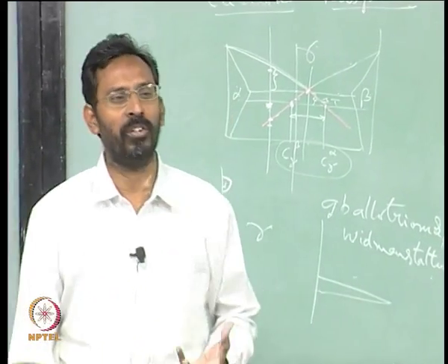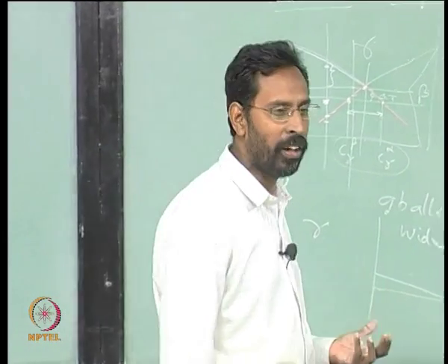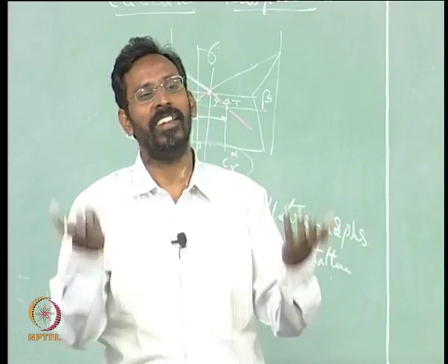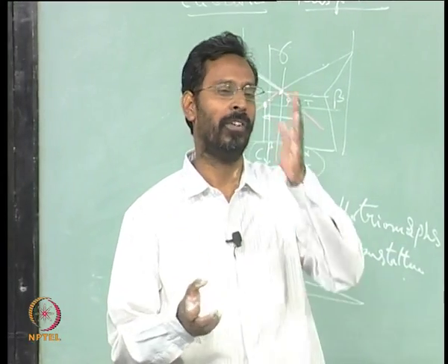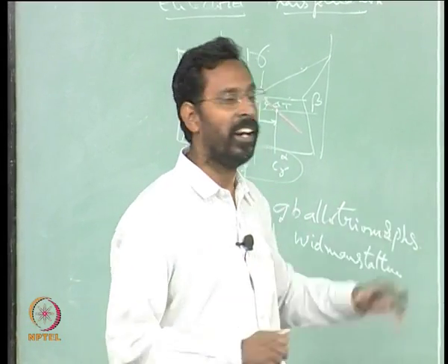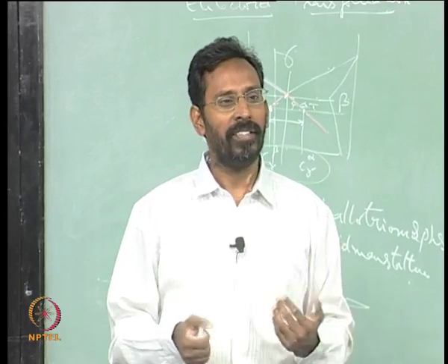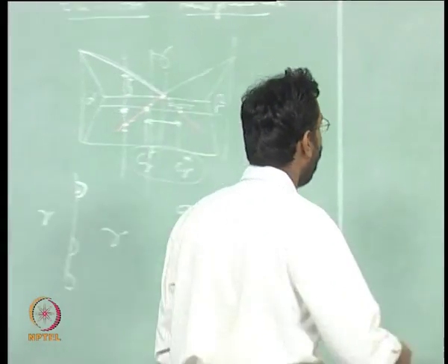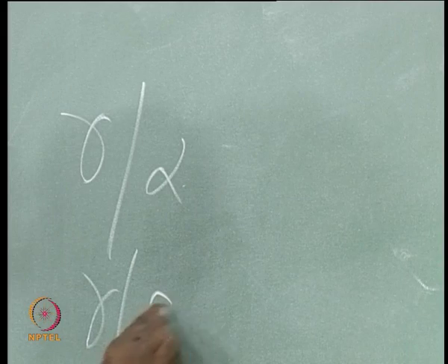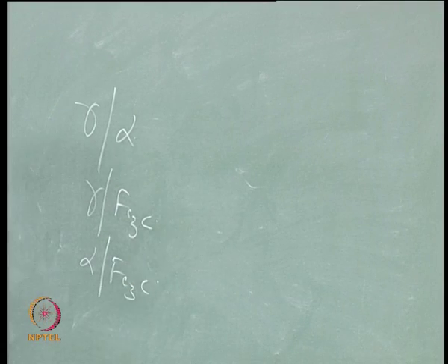You have to consider the strain also here. If you consider the strain, particularly because there you are talking of nucleation of the cementite inside the liquid, isn't it? If you consider a eutectic composition, let us say 4.3% carbon, the cementite is forming inside the liquid. Here it is forming inside the gamma. If it is forming inside the gamma, then you need to consider what that interfacial energy is. So I have to consider the gamma alpha interfacial energy, the gamma cementite interfacial energy, and then the alpha cementite interfacial energy. These are the three interfacial energies I should bother about.